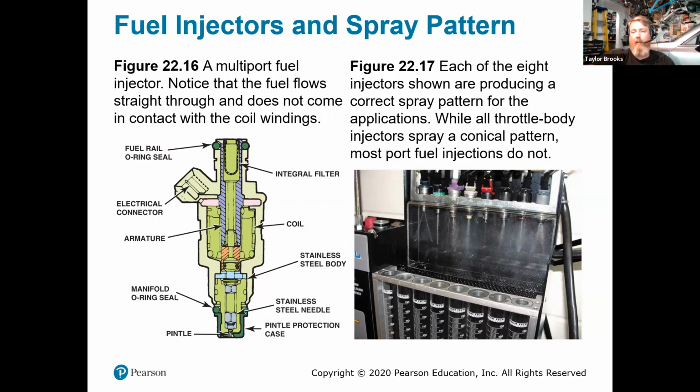Now, the spray pattern, again, is going to be a little bit unique in that it's going to go through and around the stem of our valve. One of the other things that we want to make sure we're paying attention to is that the volume of the injectors is all going to be the same. Ideally, we're trying to atomize the fuel into the air so that we have that rich mixture. When I say rich mixture, I should say a consistent mixture. That's probably a better term for our engine to operate correctly. But we also want to make sure that all the injectors are flowing the same.